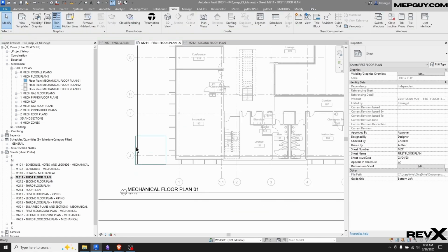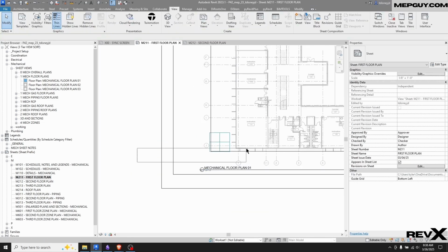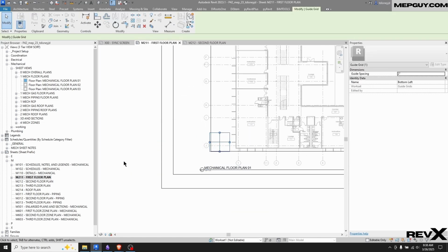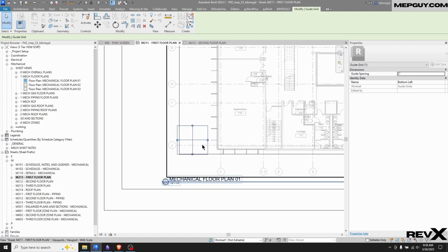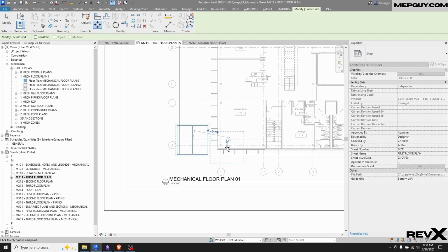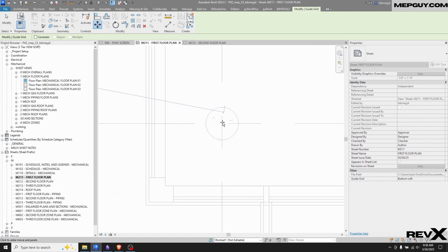So if I select it, and to select it I need to box select it from the left like this. Then I'm going to move it. MV is the shortcut for move. Going to go on that crosshairs. And it's not going to snap to these grids.